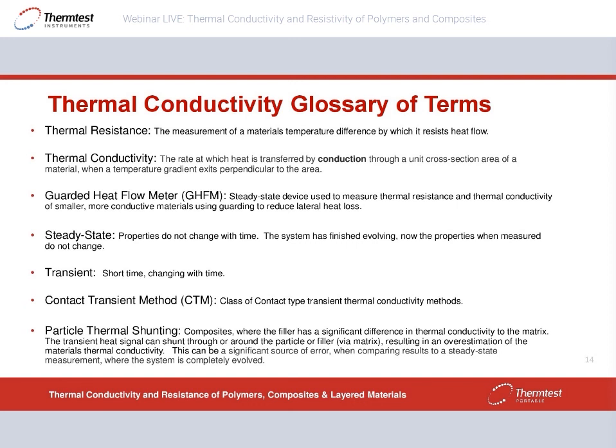So if you don't care about the other direction, you can test your materials in confidence that you don't have heat loss radially. There are lots of papers describing that and proving it experimentally. If you're interested in measuring the other directions, you could prepare a sample and measure from another direction. Another question: can we measure a rectangular sample? No. This requires 2-inch diameter only, and the thickness can vary.